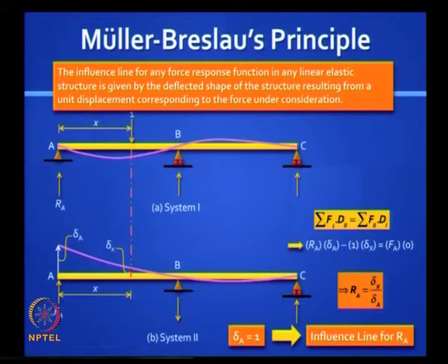And an interesting thing to note, and I want you to give me the answer for this, is that if the structure is just rigid, if it is statically determinate, the influence lines are always straight lines. If they are indeterminate, as in this case, they are not straight, they get curved. Why is that so? It's a good point to reflect over.